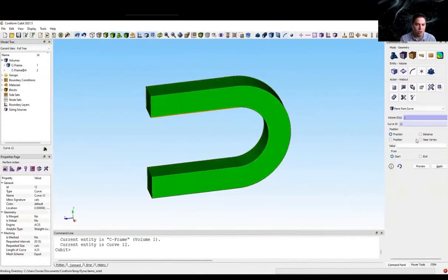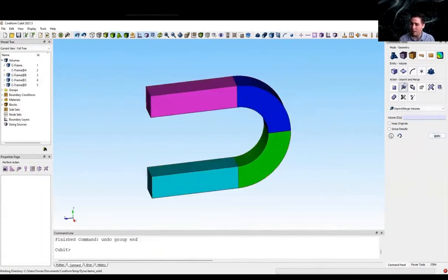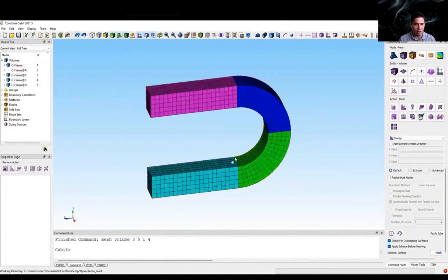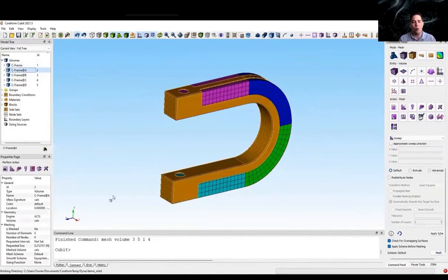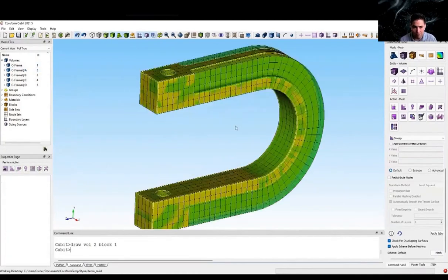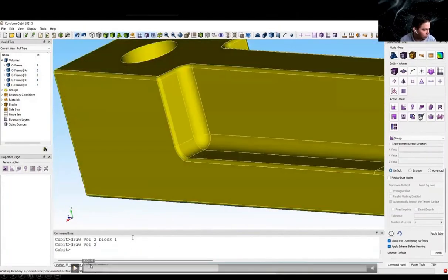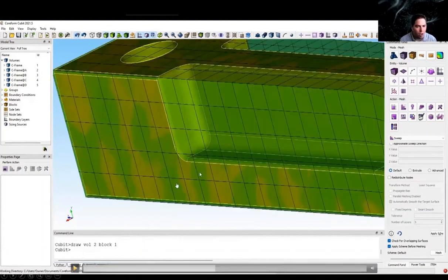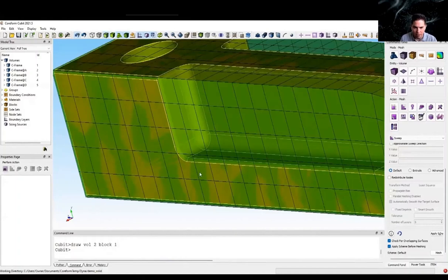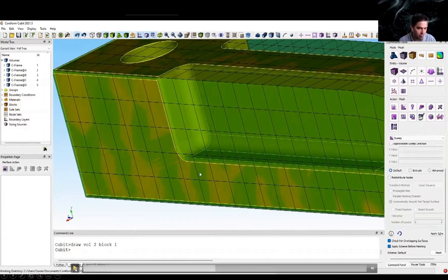Now, I could just build a mesh there, but I wanted to show that you can do all the traditional FEA pre-processing techniques like webcutting and imprinting and merging to design your computational domain how you'd like. As you can see here, I might try to pause this real quick. Oops, missed it by just a hair. So we can see all of those small features are still present in the physical domain, but they are immersed by this bounding U-spline computational domain.